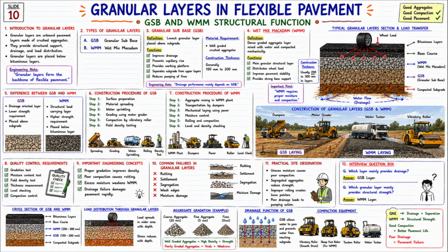Main granular layers are shown here. A. GSB. Granular sub-base. B. WMM. Wet mix macadam. Now the function of both layers is different. GSB is mainly for drainage and separation, whereas WMM provides structural strength. Now let us look at the third topic.